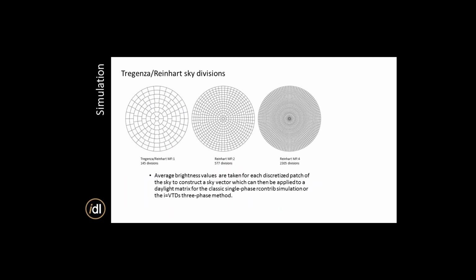Okay, so to cover the daylight matrix just really quickly here, how we would approach this, instead of obviously doing 8760 different simulations for each time step, we would divide our sky into pieces, and then we would account for the contribution of each patch to the outside of that fenestration. And that would become a matrix, basically, a series of coefficients that you can multiply or add weather data to, or different sets of weather data to.